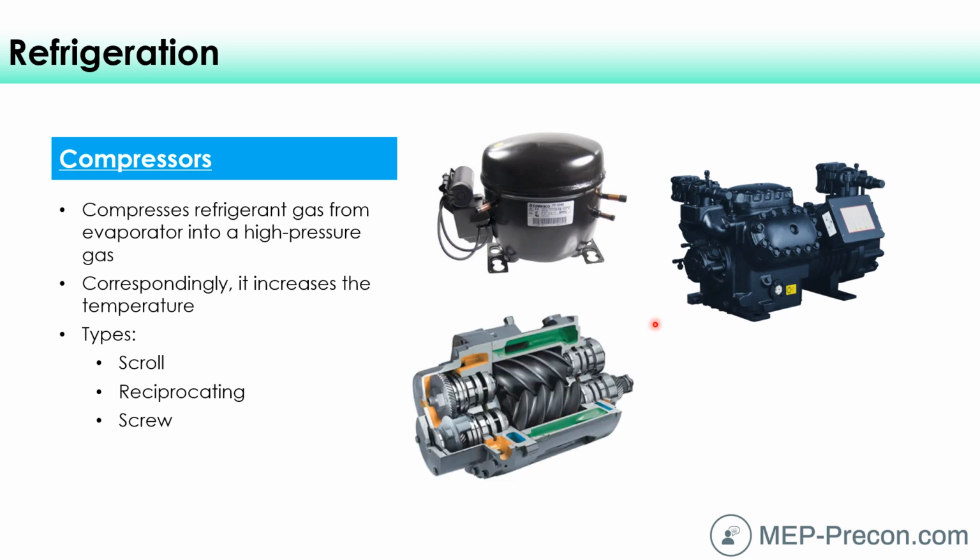Then there's a screw type compressor. And okay, here's a nice cutaway here. So this works kind of similar to a jet ski or something like that, a jet drive watercraft, where these things spin around a whole lot, and these screws interlock, or they interface, and as the refrigerant comes in, it does a really good job of compressing it at a higher pressure on the other end.